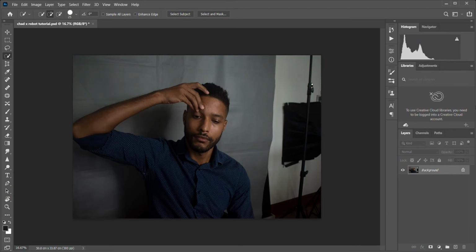So today what I would like to show you is how to easily manipulate your image in Photoshop. So first, all you have to do is open your file in Photoshop, and then let's make a copy just to make sure that we have a backup in case you mess up. Ctrl J on your keyboard. Now you have the layer 1. You can keep it as layer 1 for the name of the file, or I'm going to change it to Chat image.